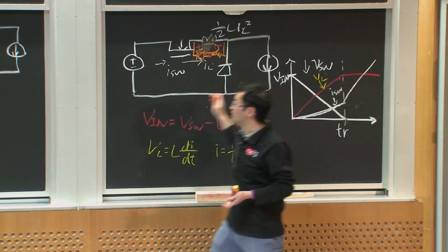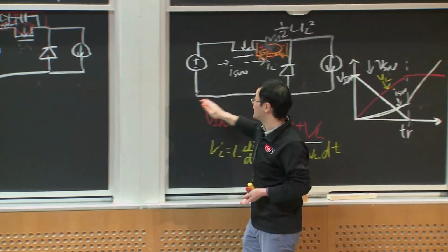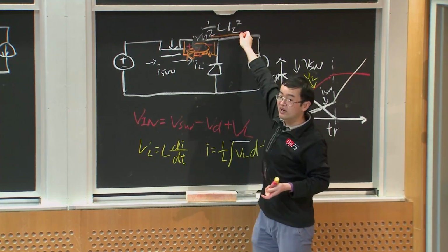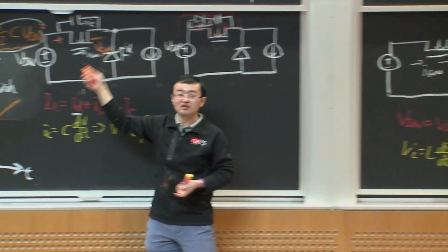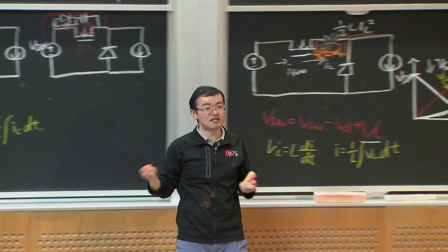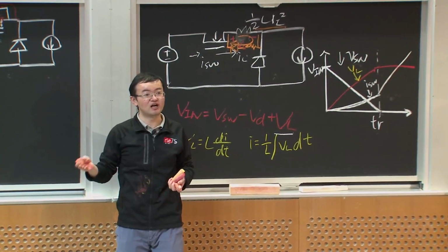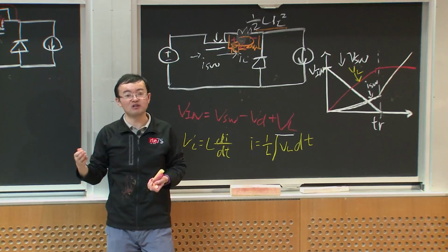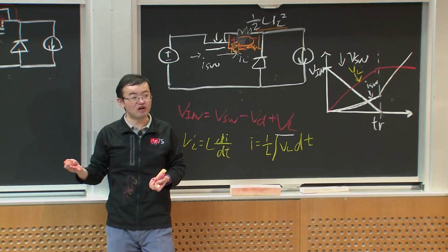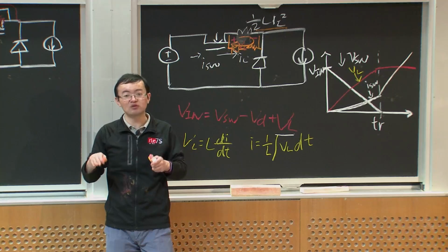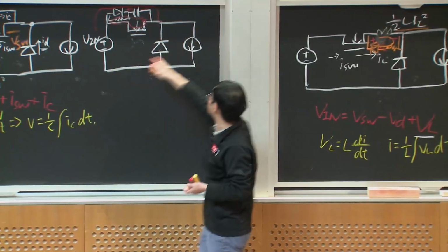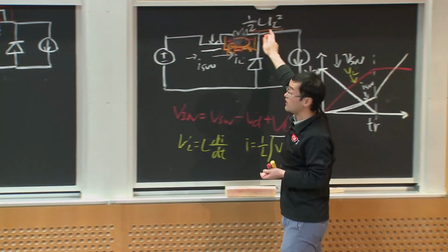So this is only where we care about the turn-off. This is where we care about the turn-on. And again, we dissipate this amount of energy fully. So in practice, we can design some snubbers that deal with both the turn-on and the turn-off. For some semiconductor devices, we may care more about the turn-on, or we may care more about the turn-off. So we can select a trade-off, like we want to mitigate the turn-on loss more, or we want to mitigate the turn-off loss more. And also here, we dissipate the energy of half C V squared and half L i squared.